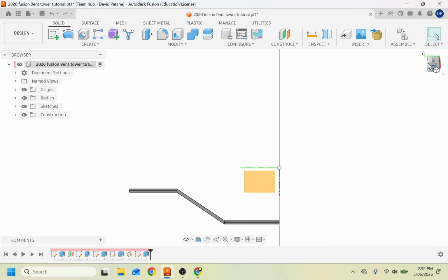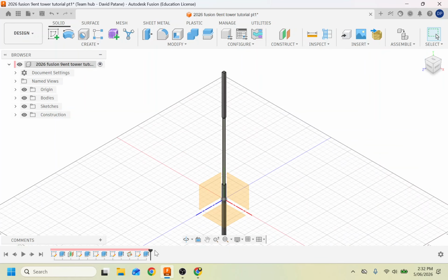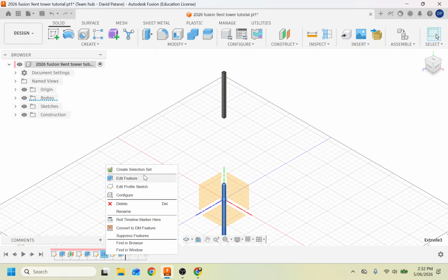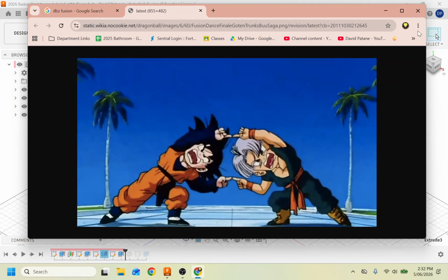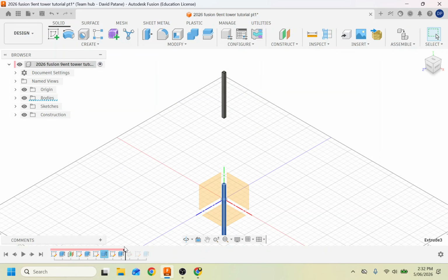It also means if you want to go back, you can drag this thing all the way back here, and then you can start making changes. Now, if you make any changes from this point, like if you do a new command, it's going to delete everything in front of it. So that's the options. You can either go back and right click and edit something. You can edit it and then it doesn't ruin everything else, unless that part is dependent on something else, which could potentially happen.